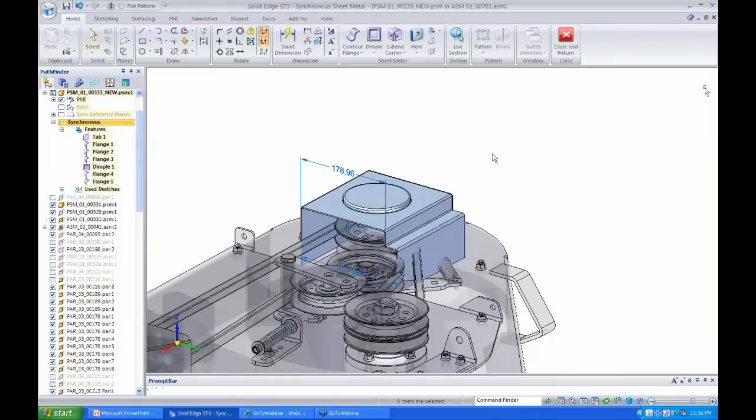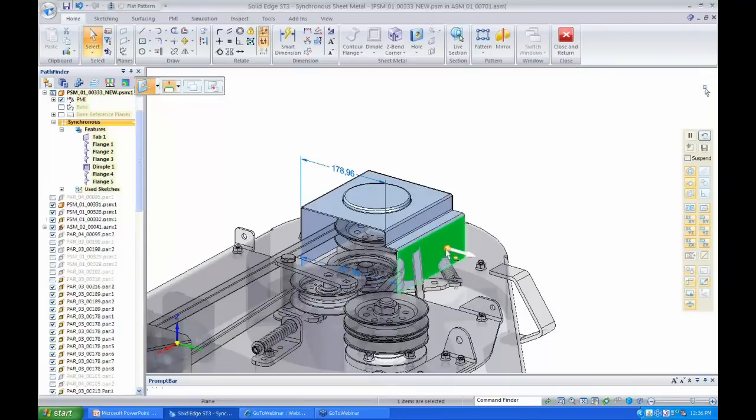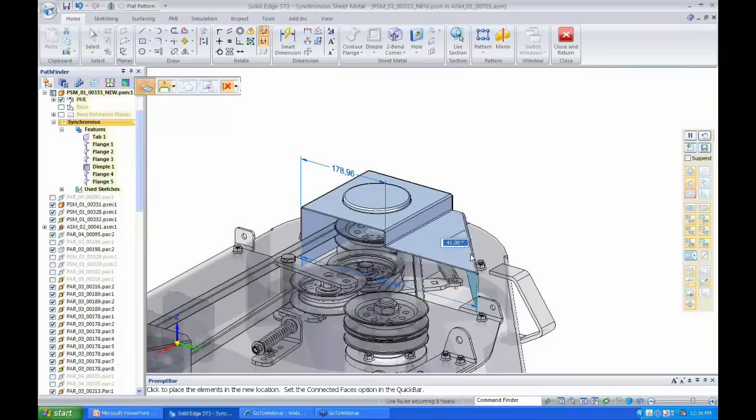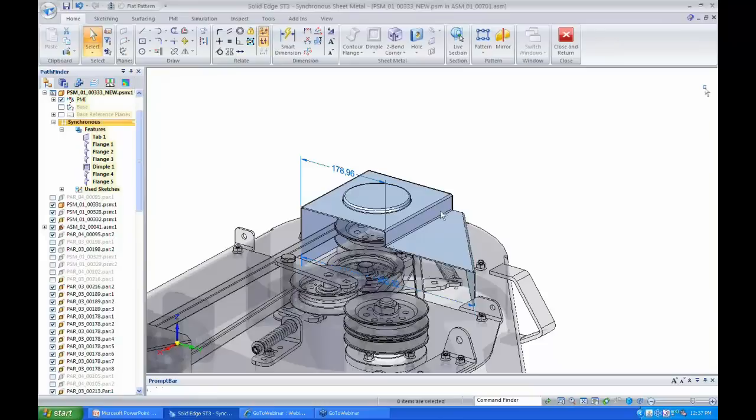Now what I'm going to do is rotate this face a little bit. So I just grab the face. Now I can orient the axis of the steering wheel. In this case, I don't want any coplanar faces to be selected, so I can check my coplanar live rule option off, and now I'm all set to rotate it. So the rotation angle, I'm going to keep this as 40, and I'm going to repeat this operation on another face. The only difference is I will just change the angle instead of 40 to 20.